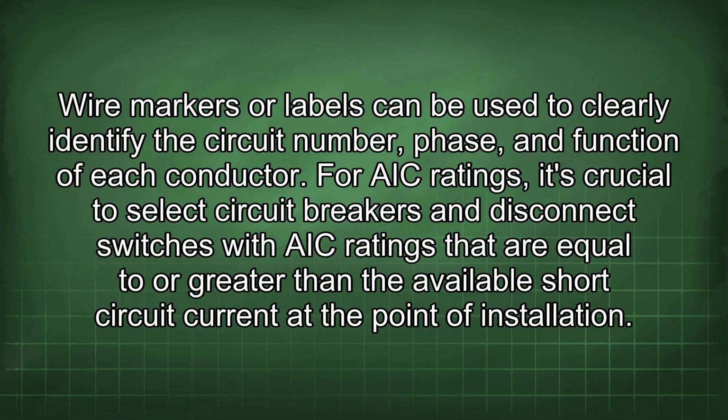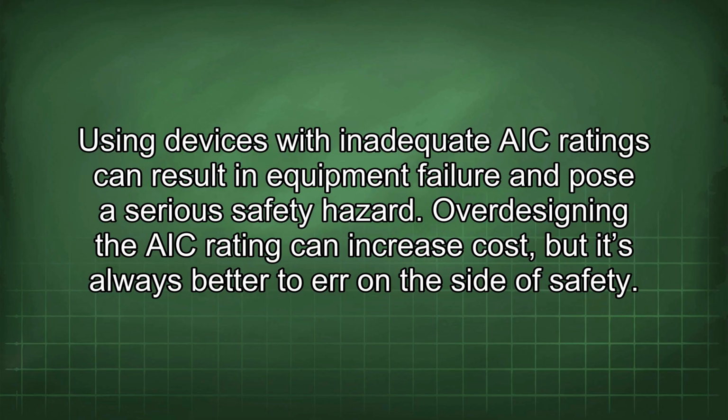For AIC ratings, it's crucial to select circuit breakers and disconnect switches with AIC ratings that are equal to or greater than the available short circuit current at the point of installation. Using devices with inadequate AIC ratings can result in equipment failure and pose a serious safety hazard. Over-designing the AIC rating can increase costs, but it's always better to err on the side of safety.